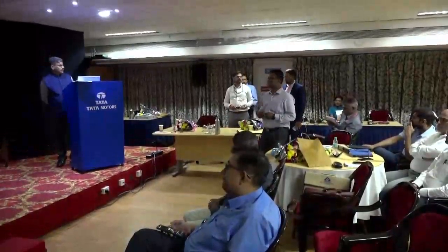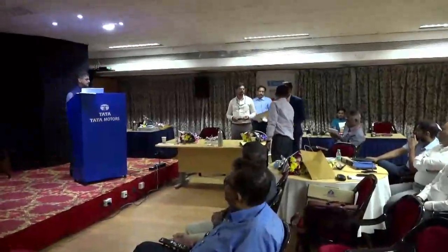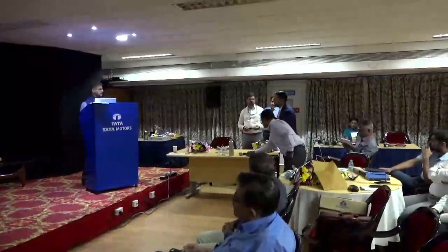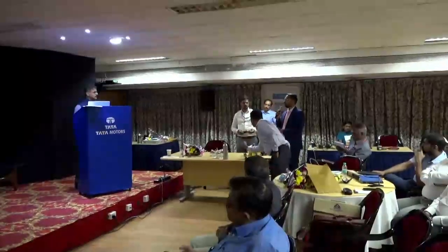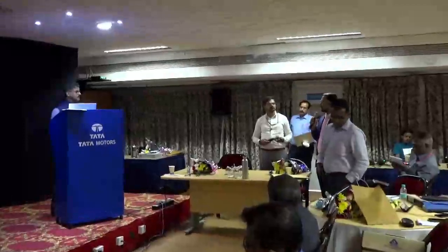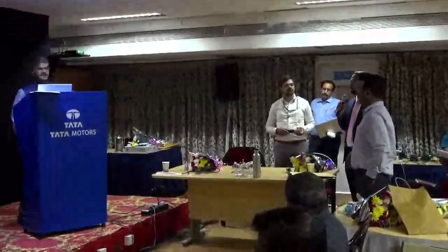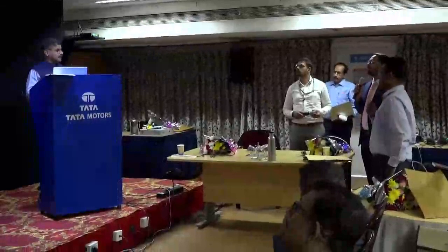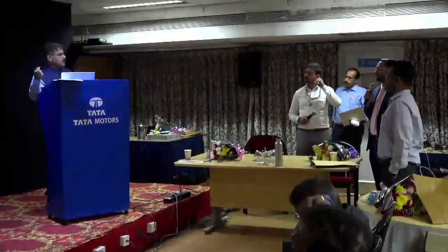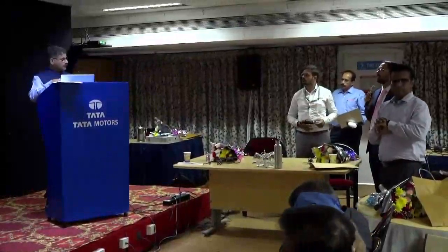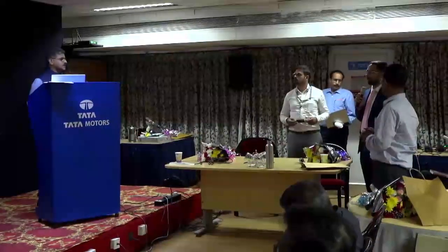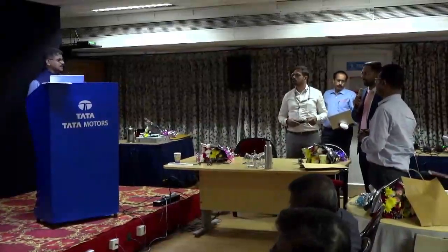Yes, sir. One question from my side. You just showed us the modified way of calculating dynamic load rating for a bearing in comparison to ISO 281, which prescribes a general set of equations for calculating the dynamic load ratings. This is only what they share. That's why we are also trying to implement it. We generally follow ISO only. But the material factor, loading factor, lubrication factor and all, it will give. We are trying that. That's what I presented.